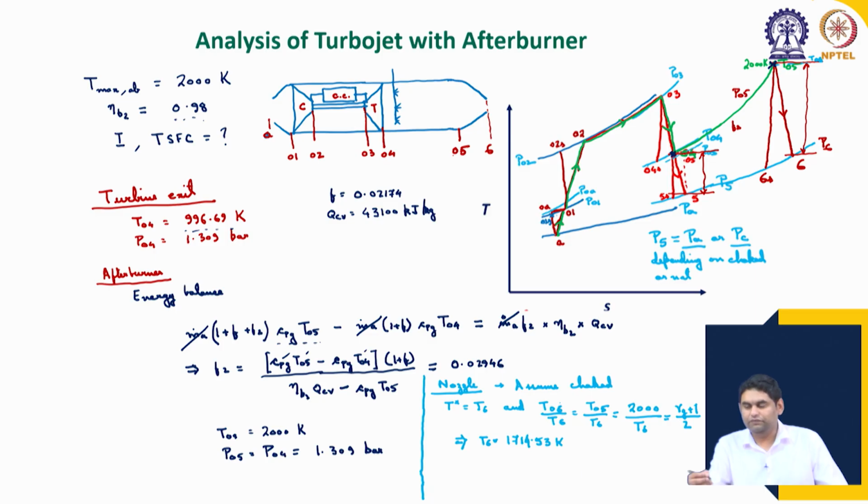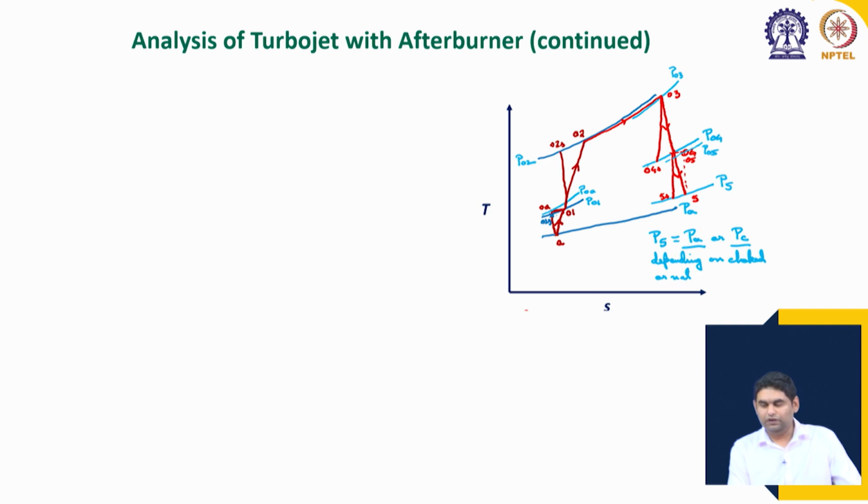So, what is the next step? We have to see whether the nozzle is choked or not. To do that, we have to find the temperature T6s at point 6s, then the pressure, and from the pressure ratio we can see whether we are at a higher pressure at point 6 compared to atmospheric pressure, or the critical pressure is lower than that. If it is lower than that, then our exit condition will be atmospheric pressure. That is our next step. So, we will continue this.